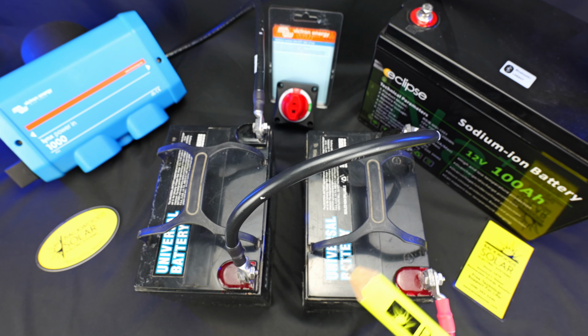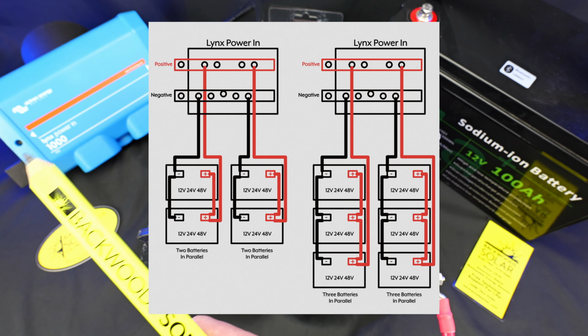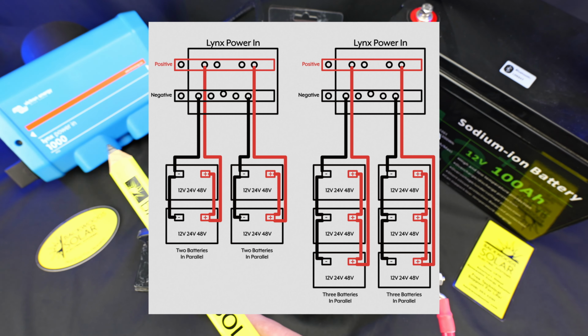So especially with lithium, it's really important to make sure we have equal cable lengths and diameter, as well as utilizing preferably a bus bar like the Lynx Bus Bar system to ensure equal resistance to each string or group of batteries.